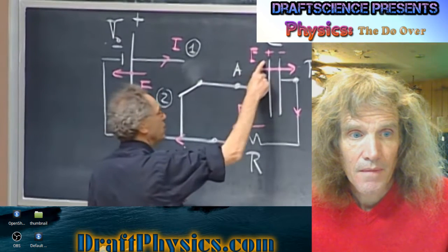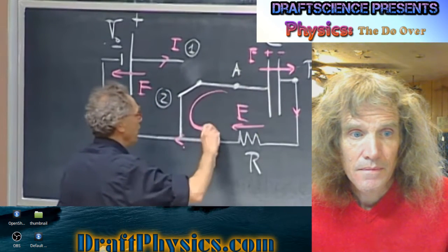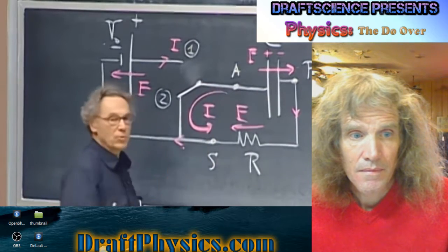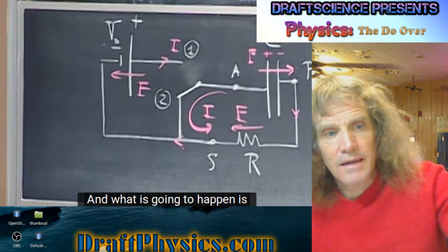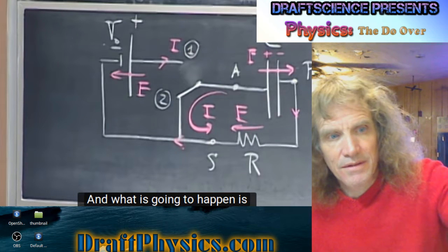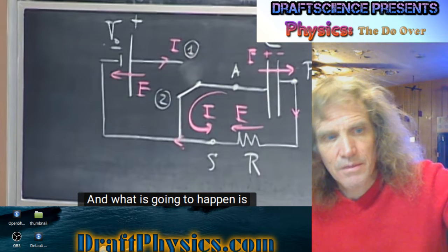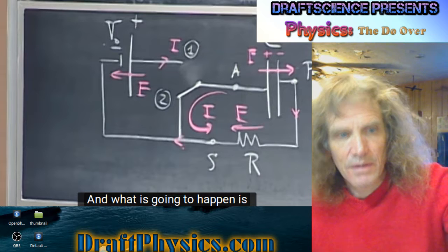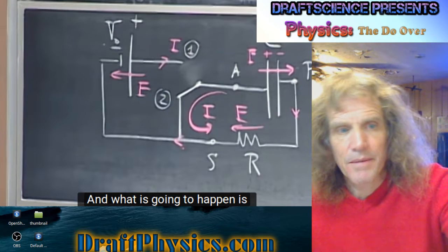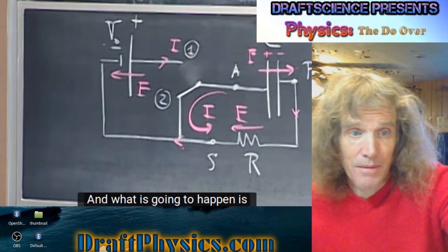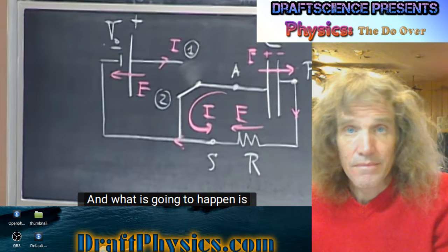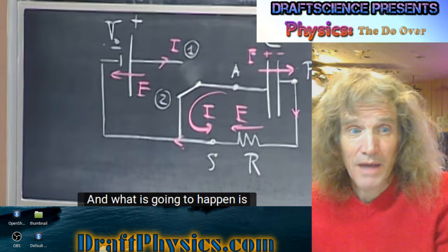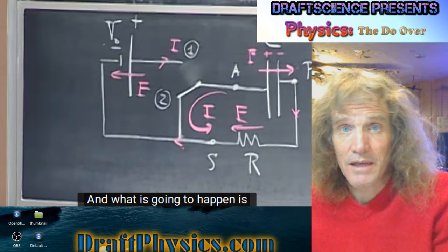Of course, this side is positively charged and this is negatively charged. So now you're going to get a current which is going to run counterclockwise, in the opposite direction. He's just disconnected everything on that side. Even though he just took out the switch, he takes out the battery. So now he's just closing the circuit between the capacitors. Now the capacitor is the battery, and the battery is just going to be shorted essentially through the resistor. It's just going to work like a battery, and it's going to run out, and that'll be it.